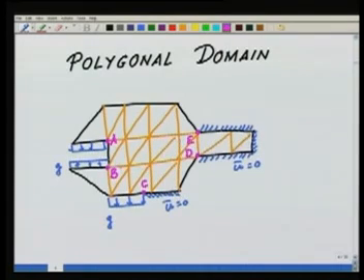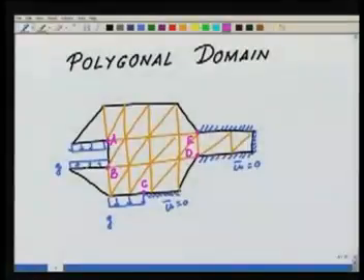which are interesting points. Imagine this as a problem of elasticity, where I fix the displacements here and I have this kind of a corner. I expect stress concentrations to happen. Similarly, at these points A, B, C, because here the boundary condition is changing suddenly. I have one flux condition and suddenly I am fixing the displacement. So at these points I would expect stress concentration.